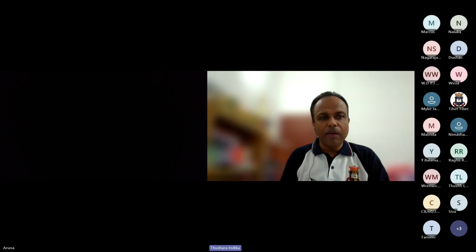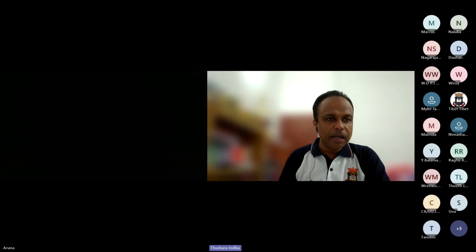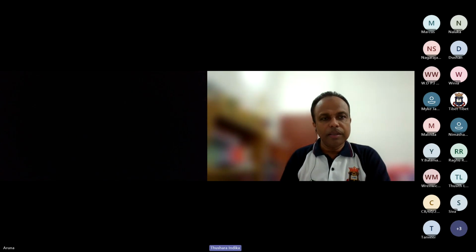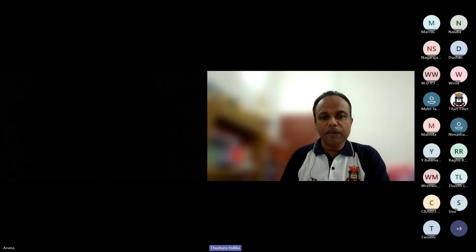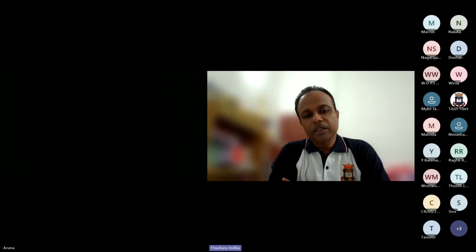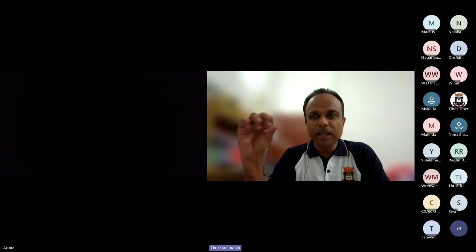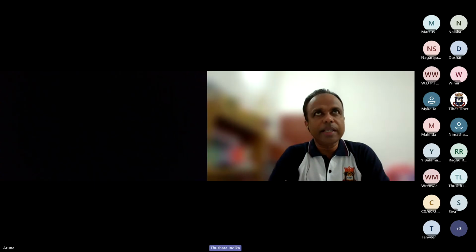Right. So what we have done is we have uploaded the drawing through drawings, add drawings. And this is where you can add the drawings, and once you have added the drawing, you want to measure something. So the protocol in CostX is that, of course, you need to introduce something called dimension groups, right? So if you want to measure PCC, it's almost like your BOQ item, the item that you are going to measure from CostX.